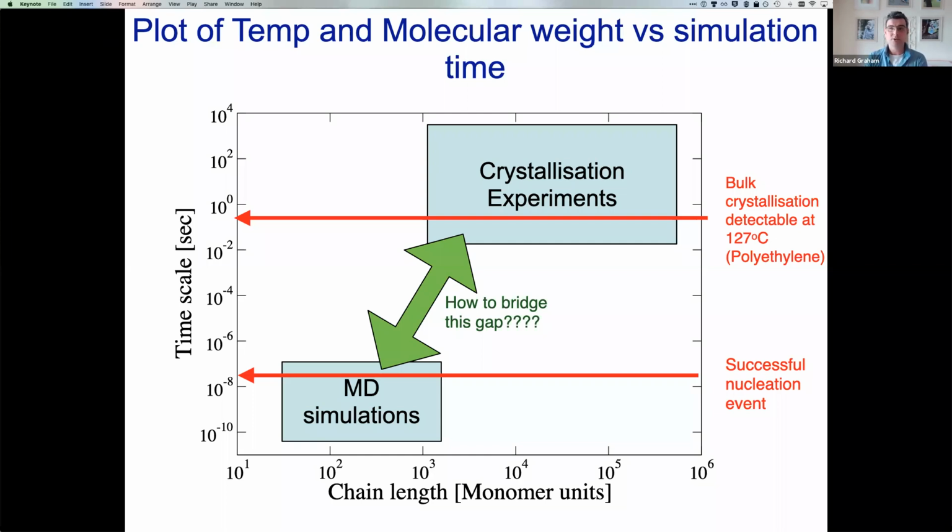And so what it means is that anywhere there's an imperfection, there's a reasonable chance that nucleation is more favored there. What tends to happen with beer glasses is that any little nick in the glass, or even the glass itself, will preferentially create nuclei. If you look really closely, you'll see specific points on the side of the glass that create a stream of bubbles. That's because the nucleation is a bit easier at these sites of imperfection, generally because the surface energy is a bit lower. And so that tends to dominate the nucleation in something like a beer glass.